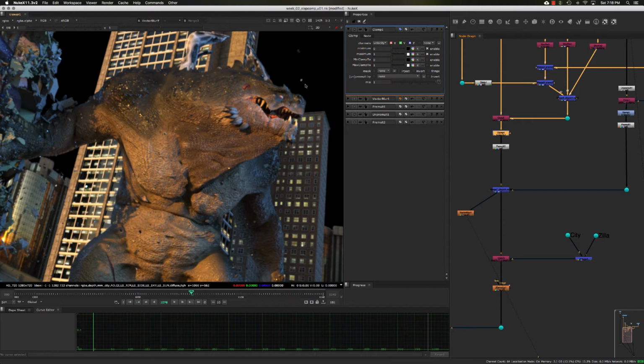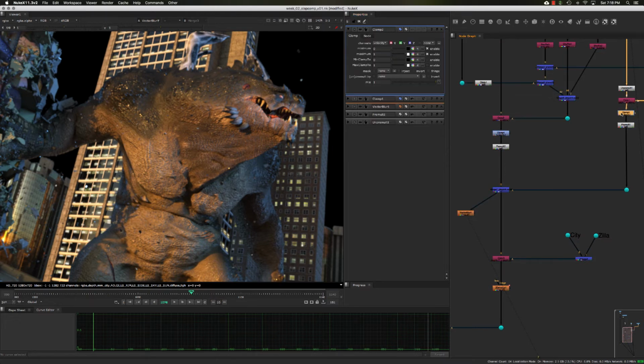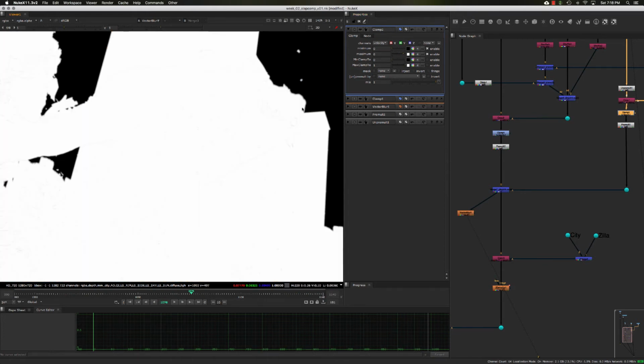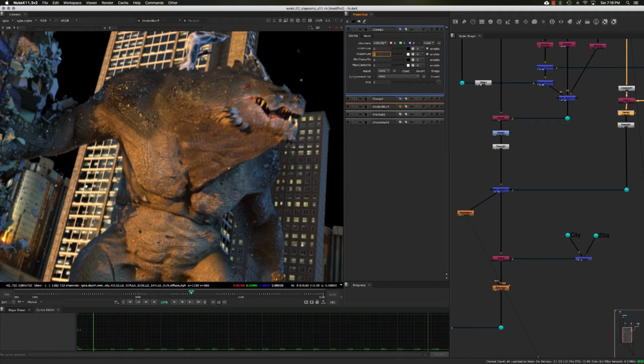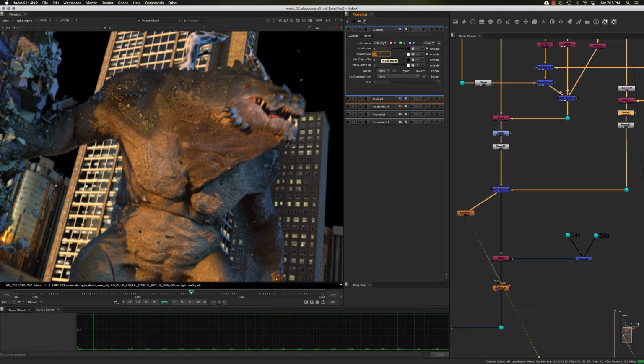And in this case, what we want to do is maybe set the maximum instead of 1 to maybe a value of 6. And we'll do the same thing for our Zillow clamp node. We'll just set that to 6 as well. And you could see we're getting more motion blur as you'd expect. So you could take this up as high as you want. We could maybe even say like clamp it at 16.